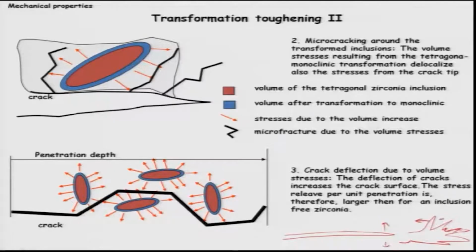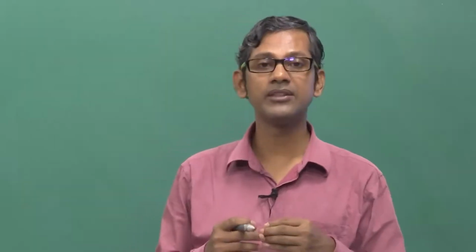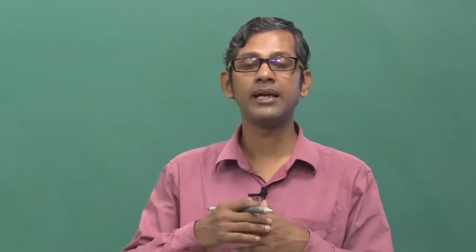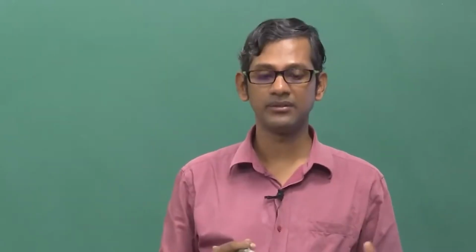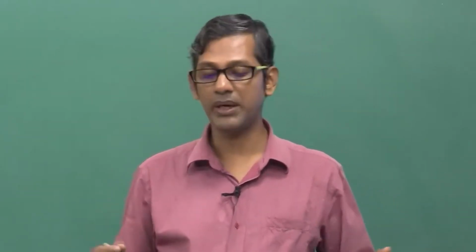Each of these cracks requires a stress to move, because of surface energy: as a crack moves, it creates two surfaces, very simple. So as one crack moves, the increase of the surface energy is smaller than with many branch cracks. That is what is known as micro cracking.